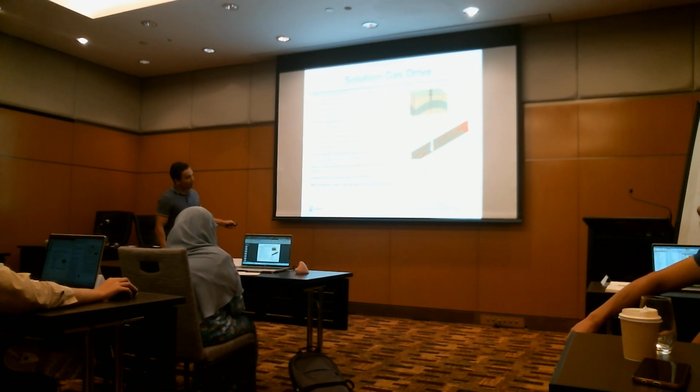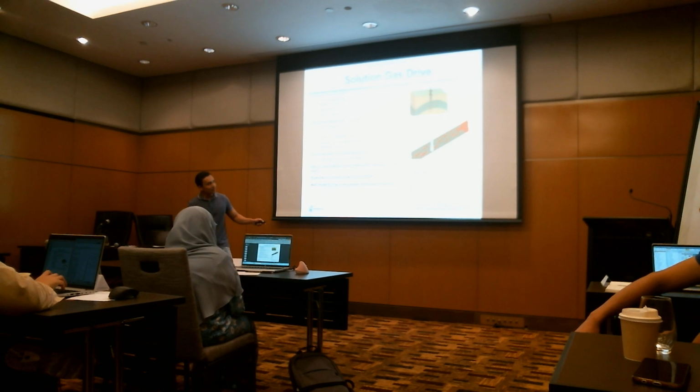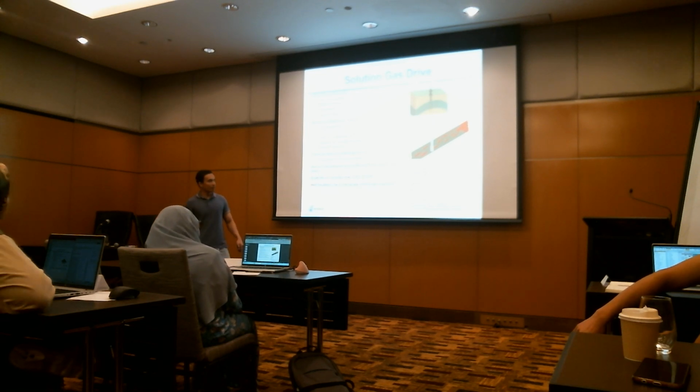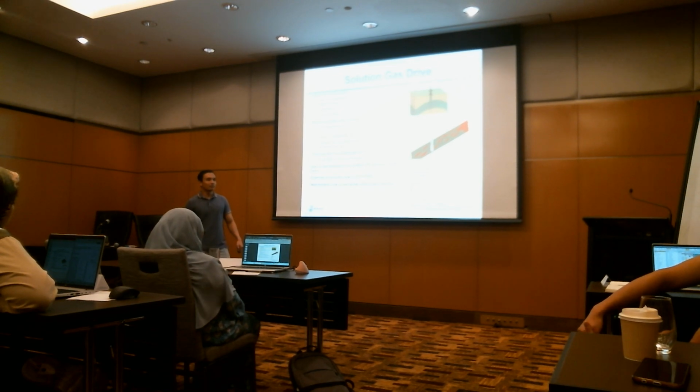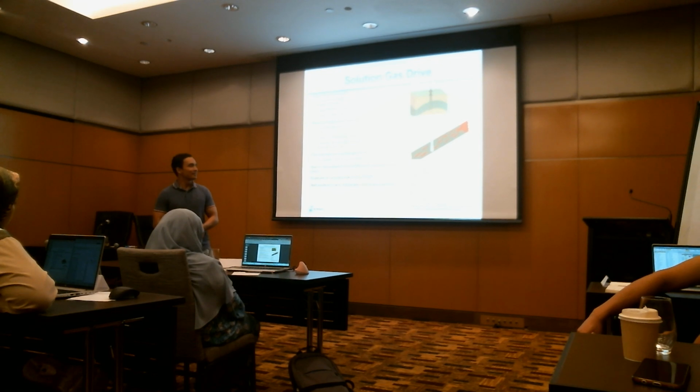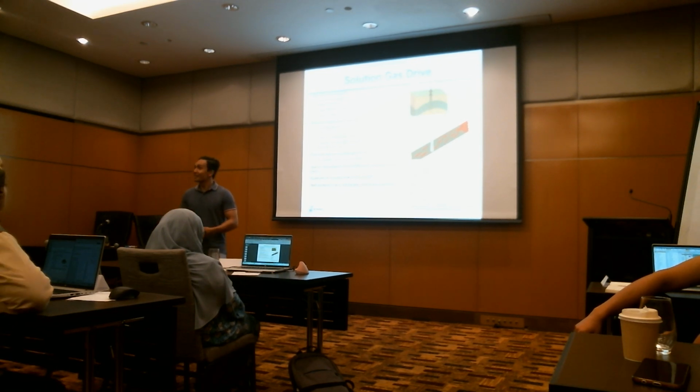Now come back to here, 2 to 3. What happened actually? What do you guys think? Why does it go down? Pressure drop? Pressure drops a bit, but I was going to ask you, because at the onset when you reach bubble point, why did the GOR drop? It's the solution gas. Yes, it's solution gas. But what happened here is there's a slump here a bit.